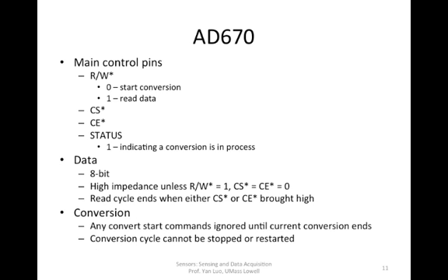For a data bus, it's a bus, so many devices will be connecting to this bus. Okay? So you can have this ADC, you can have a memory component, you can have all other different kinds of things connected to this data bus. But since it's a bus, you do not want 2 components outputting at the same time.